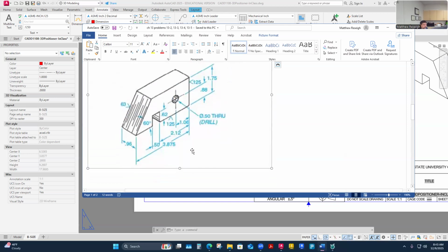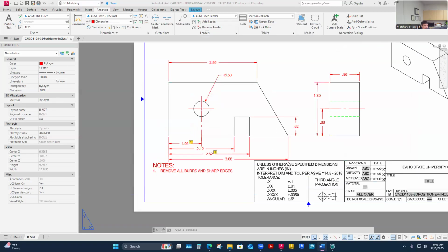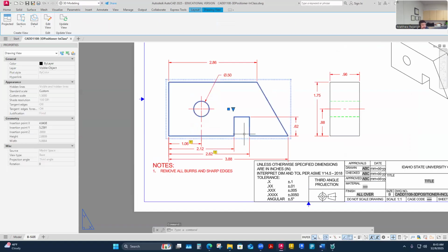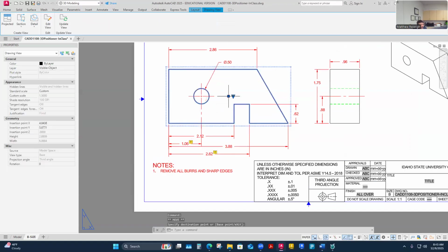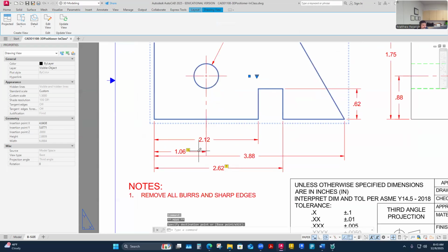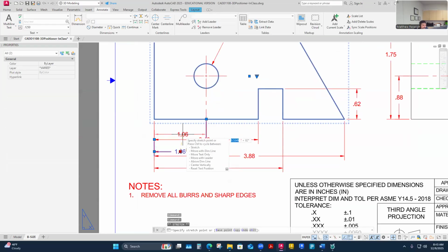So the other things I'm going to drop here: no surface finishes, and don't worry about the description on this. Just a half-inch diameter hole is fine for me. And so I'm kind of done as far as I consider. I think I've located everything. I've got a little clash here, which means I'm going to have to move my view up a little bit, which means I'm going to lose some of those associated dimensions, which is super annoying.